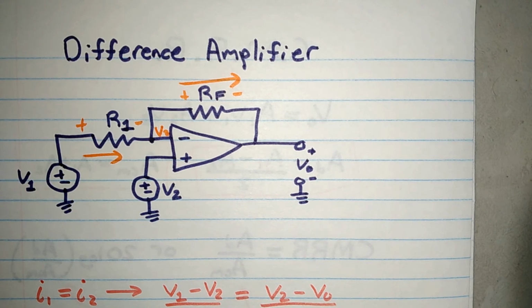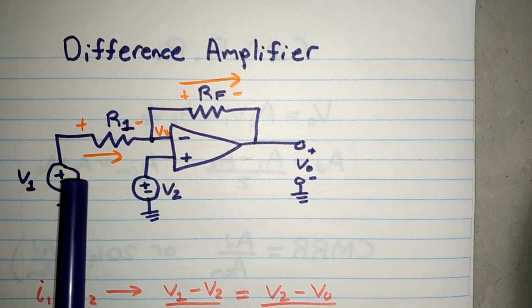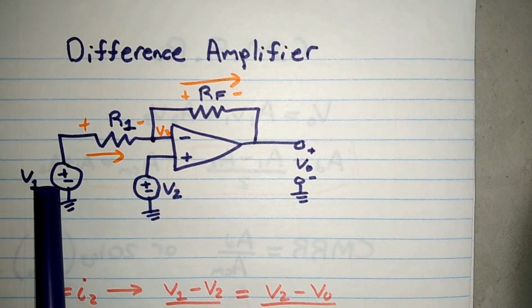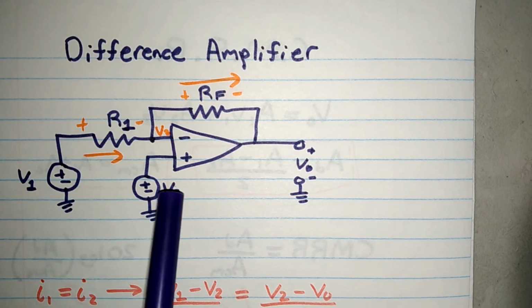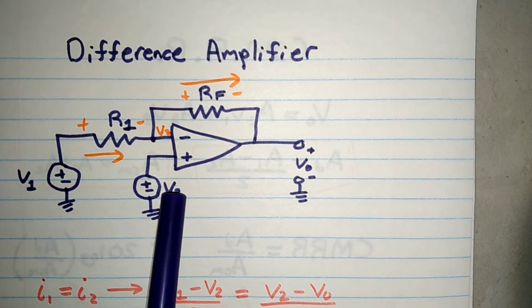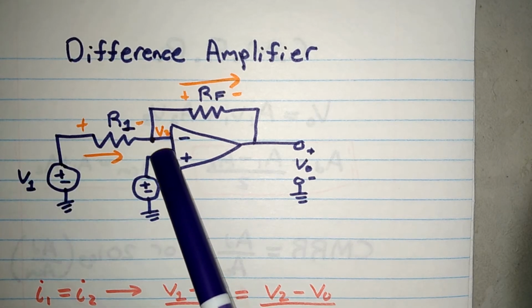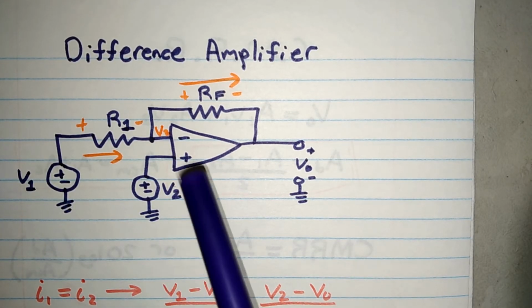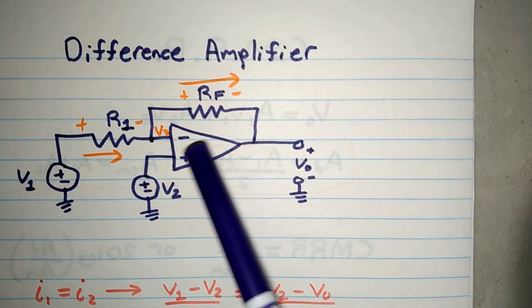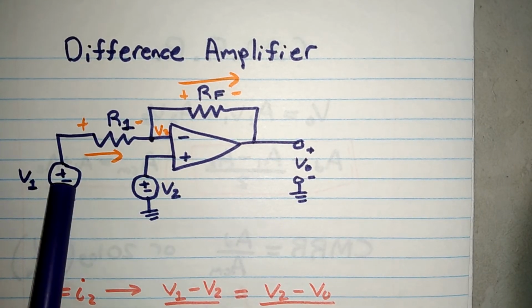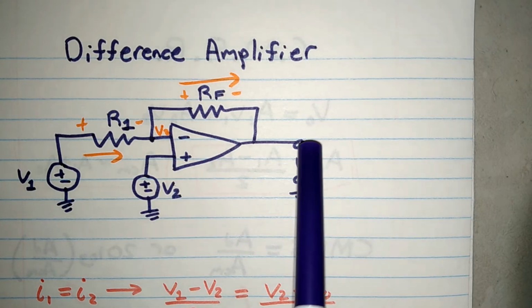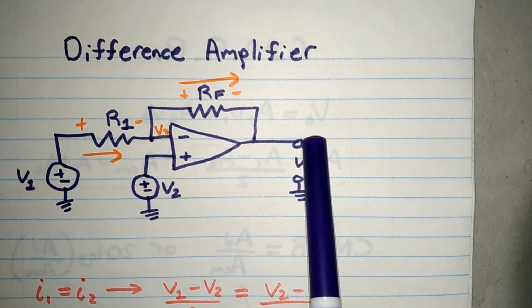And what the common mode input basically is, undesirable, at least to say it's undesirable, but what's happening and how it occurs is the V1 and V2 over here. If these two voltages are the same, let's say 10 and 10 volts, then we would get the voltage difference between these two to be 0. So ideally, we're supposed to have 0 volts.